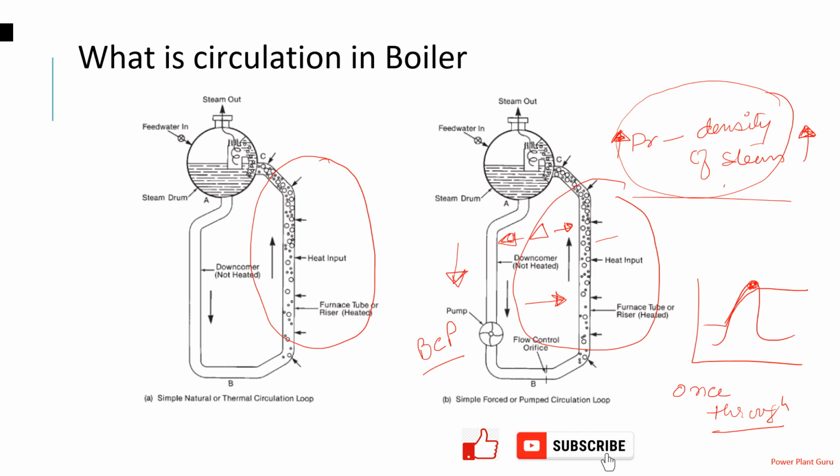There is no circulation. And those once-through boilers, if they are operating below 30% load or they are in startup or shutdown, then this BCP is required. So BCP is there in supercritical boilers also, but it is required only at lower loads or when you are starting the steam, because at that time there will not be sufficient pressure build-up, and then you have a mixed-phase flow also. So that is how it is impacted.